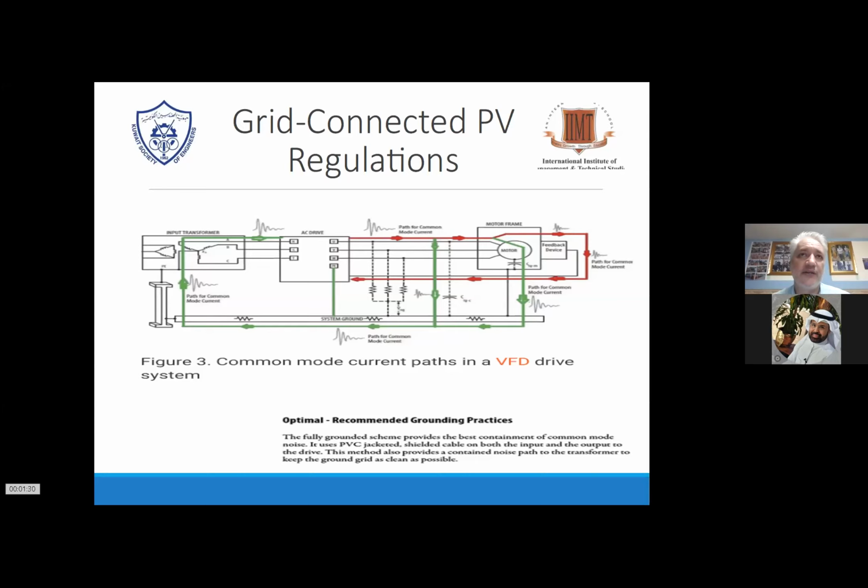Then I checked the AC boxes on the system, and I saw that it's a 5-core cable, but there was always a bridge made. They had split off the neutral and the PE, which is in actual fact not even allowed, also not in America, and then regrounded it. Sometimes they do it on purpose, like this guy, or sometimes it's a mistake and they did not know where the cable was going through. This guy installed a 30 kilowatt system, checked the other system, saw that it's not bridged at the AC boards, so he made the bridge at all 10 AC boards.